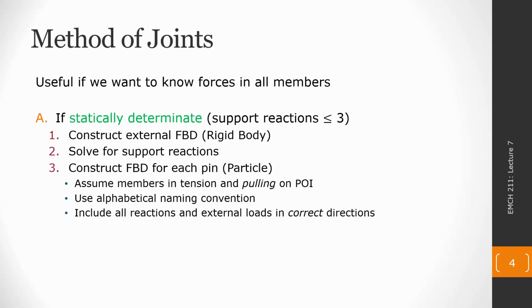So from step 2, we are going to know the proper direction and magnitude of all of those external reaction forces. When we draw these internal free body diagrams of each pin, if an external force appears in it, I'm going to recommend that in the new pictures you do draw the forces that we now know the proper direction of in that proper direction.